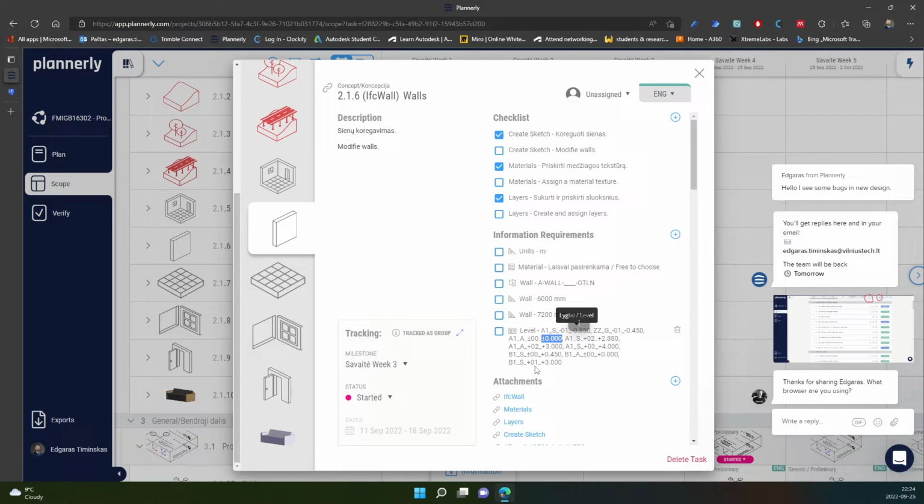If we go down, we put minus. If we go up, we put plus. And we have 3 decimal symbols after the point, so it is all in millimeters. Sometimes architects like to use just 2 decimal symbols, but when you check it out and use measure tools, you can see that not always the last number of the millimeters is in the 0 position, and my recommendation is that it's better to use the whole number to represent a real situation.